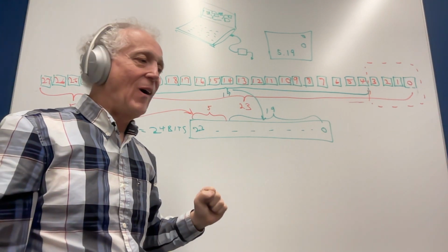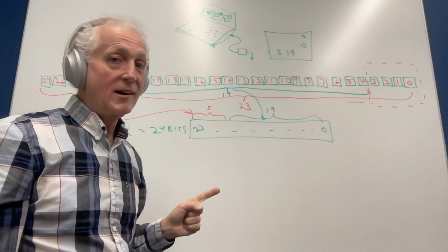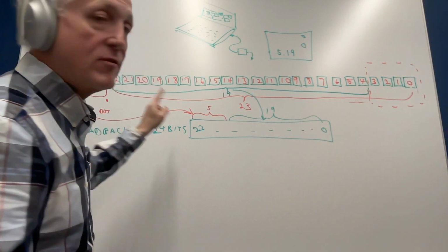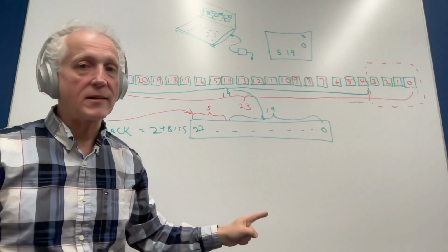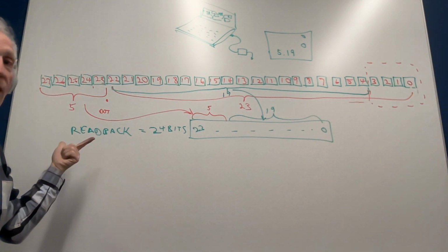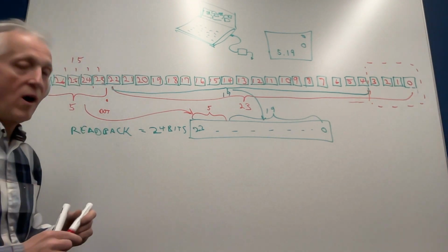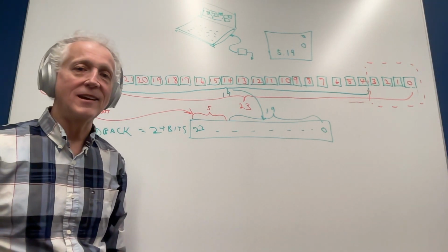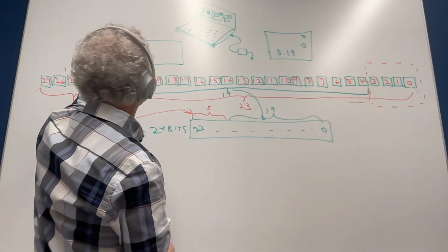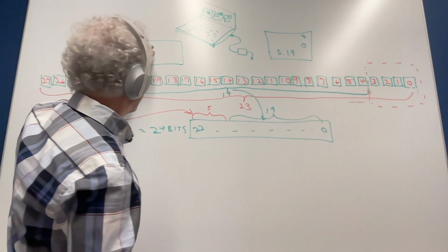Now I hope you watched my video about the number formats, because you might remember that in this 5.23 format, we only have 4 bits to represent a whole number, and that goes up to 15, 4 bits. 4 ones is 15, not 16. So we can't take the multiply block. There's a block you can do for a multiply.